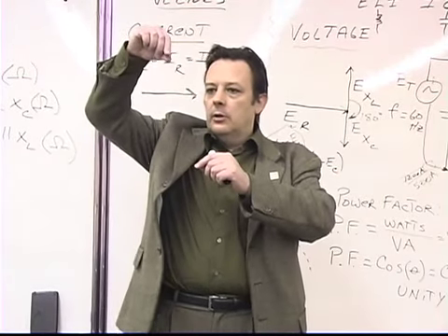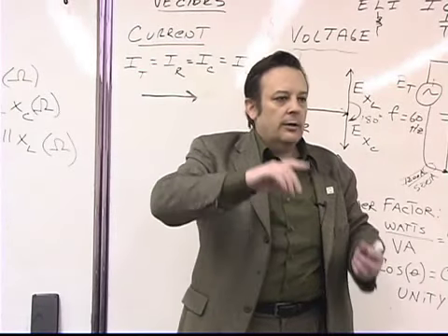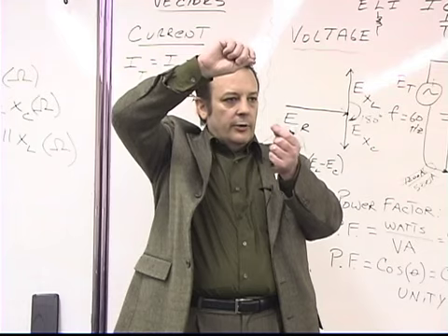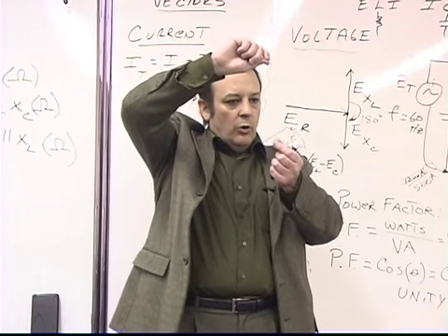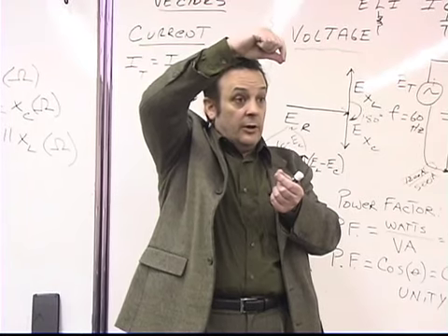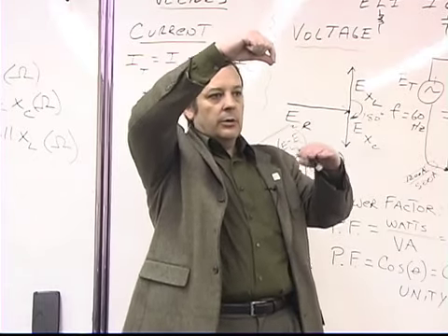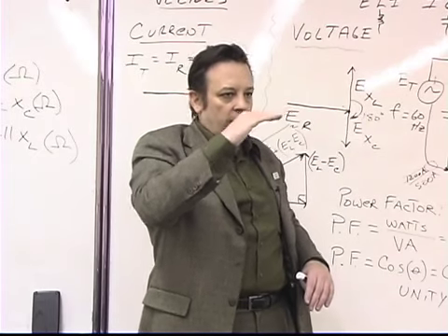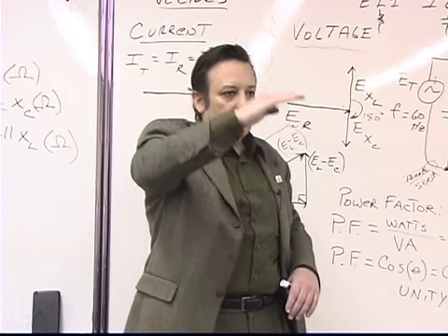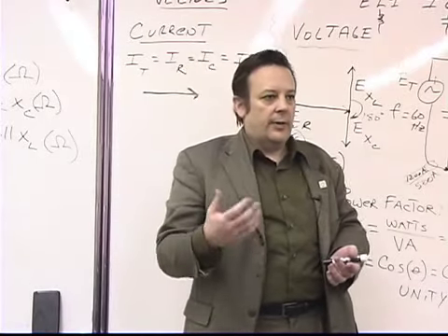So you can take a spring, just a very lightweight spring, nothing like you'd have in a car. A very lightweight spring that you could pull with your fingers. And you can hook a weight onto it, like a fishing anchor. All right? And then you can pull that thing down, and as long as you have it secured to a rigid platform, which could be your finger, you let that thing go. What's going to happen is the spring is going to oscillate. If you stand there and you count it, you can figure out how many cycles per second that thing is oscillating at if there's nothing else pulling on it except gravity. That would be the natural frequency of that spring.